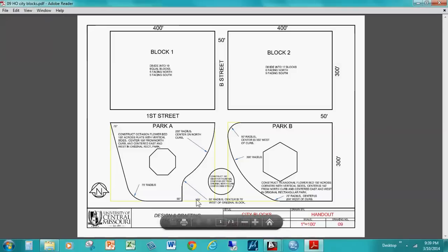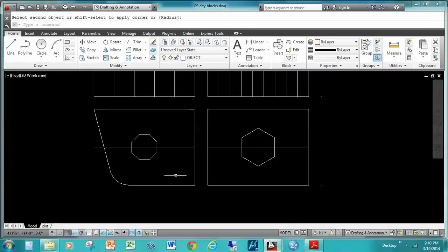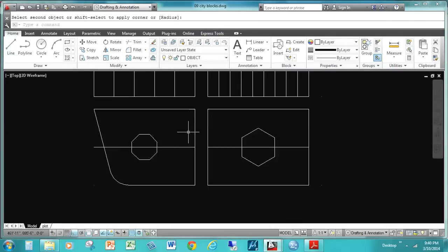But it's easier, or a simple way, to offset this line 125 feet to get to this point, right? Once we have a circle in this line, we can use the fillet command and choose the radius option 50 feet to create this shape. Okay, so AutoCAD, and here offset 250 feet, enter, select the line, click here.